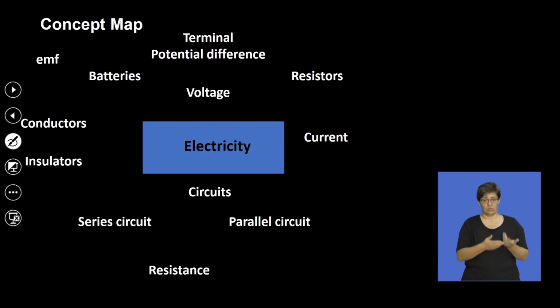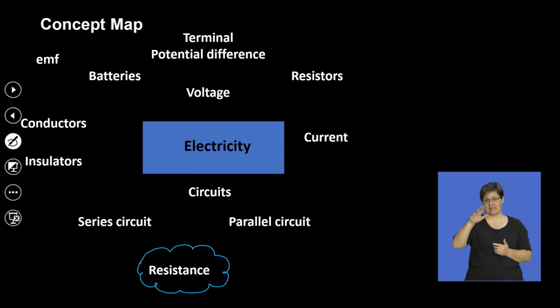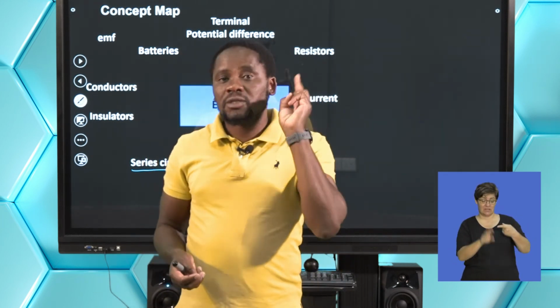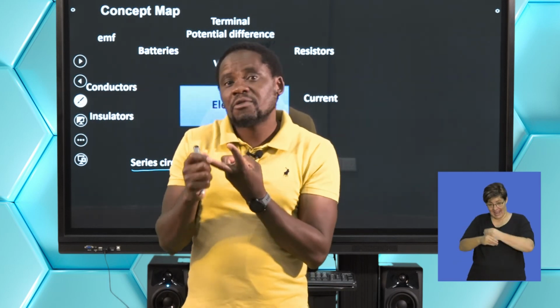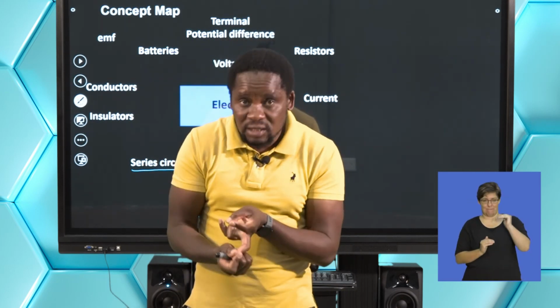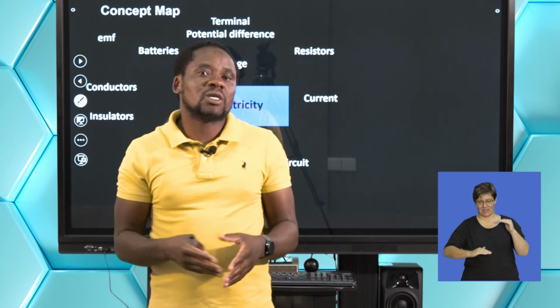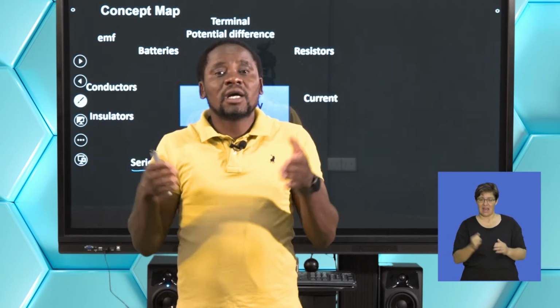In closing, we now understand what happens when you increase the total resistance of a circuit by adding more resistors in series, because that's the scenario that we had. If you increase the resistance, the total current decreases while the total resistance in the circuit increases. So as far as resistors connected in series, two very important points to take home are that increasing the number of resistors in series increases the total resistance, and at the same time it lowers the current. Hence, a series circuit is a potential divider while current remains constant.